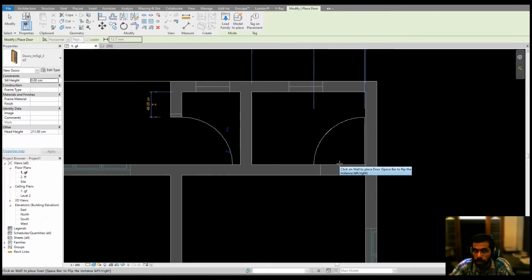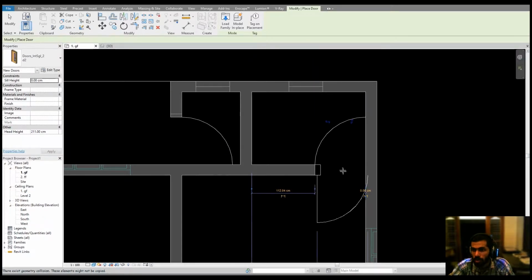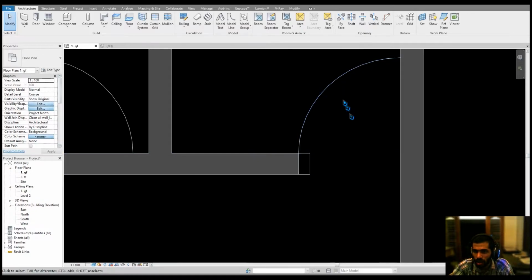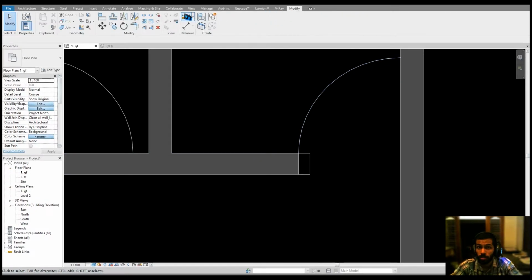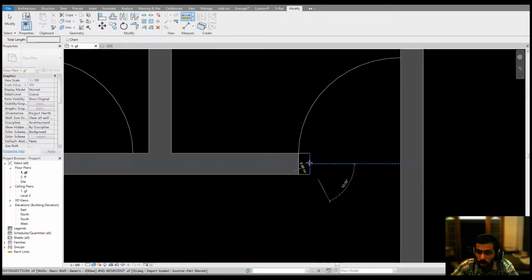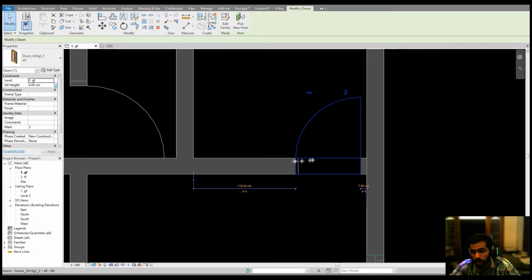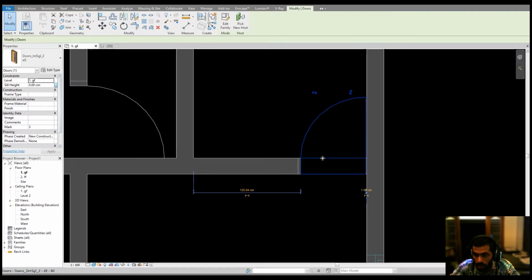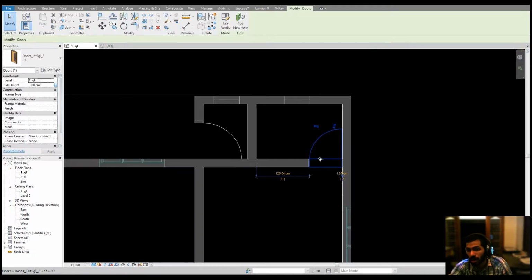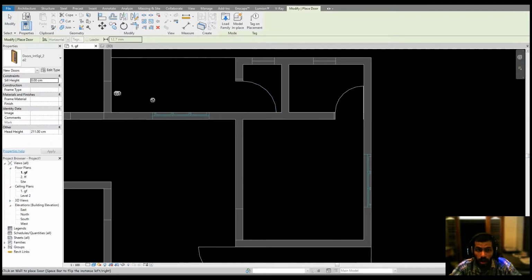I'd like to place the D2 right here, but you could say that the thickness is not fitting properly. Let me check the size of this door. That is only 79.2 centimeters, so we'll change it, duplicate it, D3 maybe. I'd like to change the size. It'll be like 76 centimeter. I'm not going super precise over there. Use the arrow keys for changing the size. Anyways, that's enough. Now let's fix the other doors here.